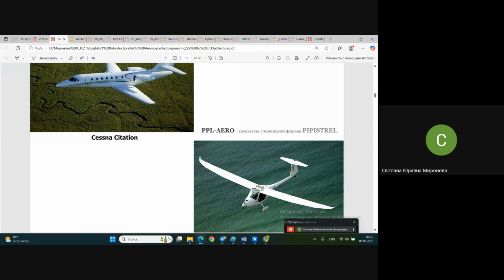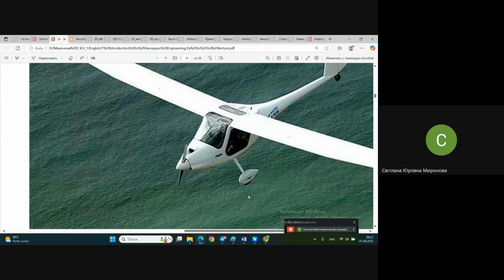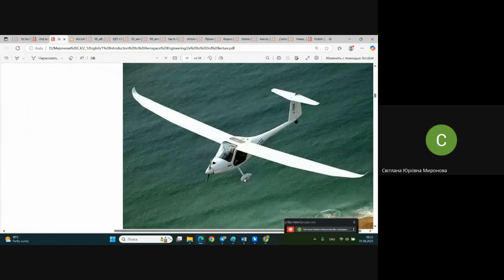Practically, it comes with cooling for the cockpit, cooling for the engine here with the prop, you see. What is this on the landing gear for? It's like screaming, I'm not retractable, I'm a slow airplane, and these fairings are necessary to improve the airflow around the wheel and to reduce drag in flight.